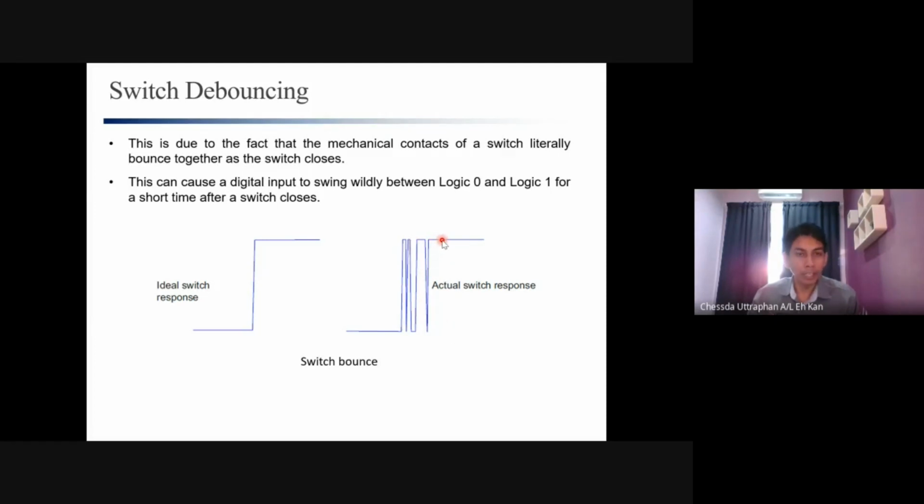If after 100 milliseconds the input signal is still 1, that is the correct input. But if after 100 milliseconds it has gone down already, that is noise only. So you need an extra code segment that can identify this.